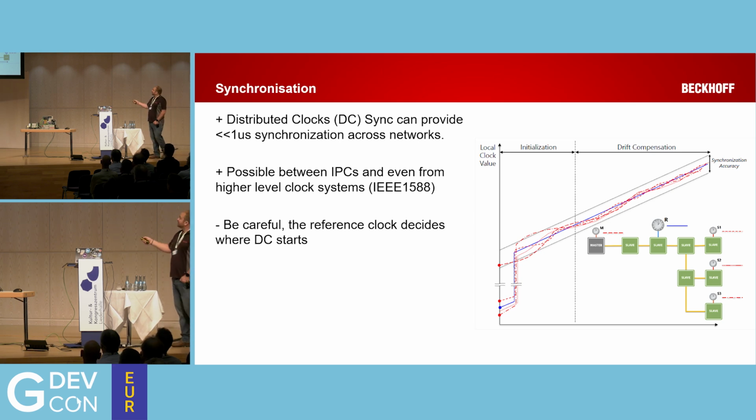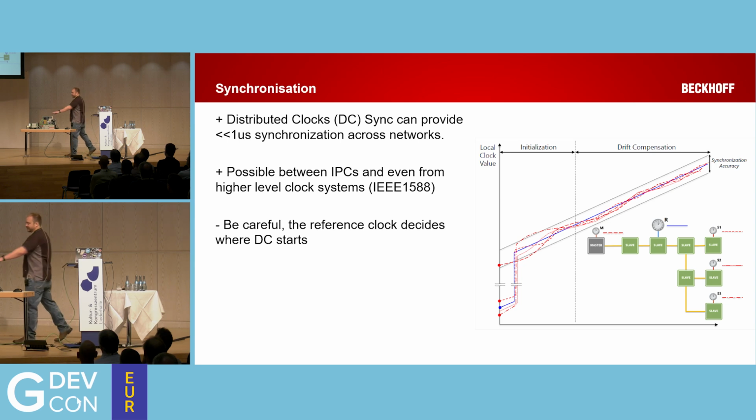The benefit of that is that we can replace this reference clock with pretty much any reference system we like. At the moment, in this system, you can see I've got a bit of hardware with me today. It's just a terminal that's in this system, so it's an EtherCAT device. But that could easily be a digital input from another system that's a very high precision input. It could be an IEEE 1588 Grandmaster reference coming in, which means you can go from just synchronizing your local systems to synchronizing systems across sites, across countries, if you want to.